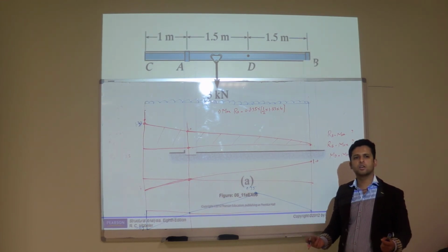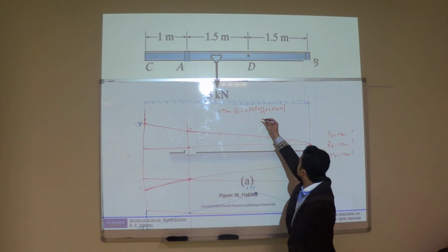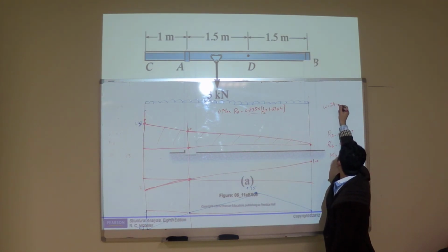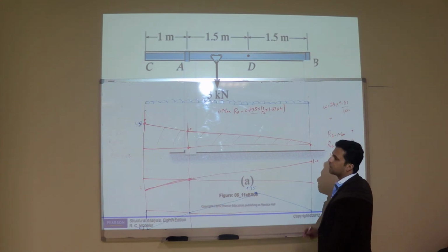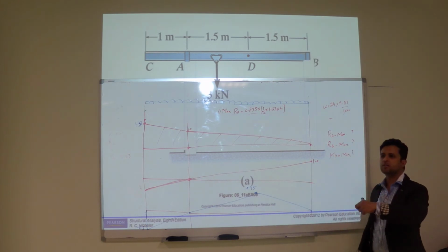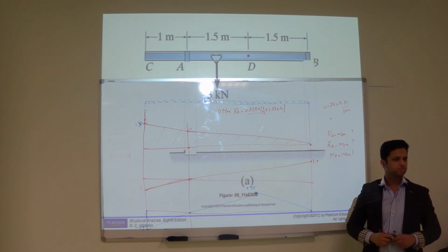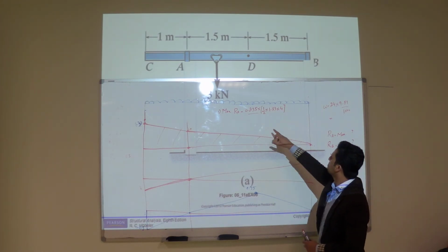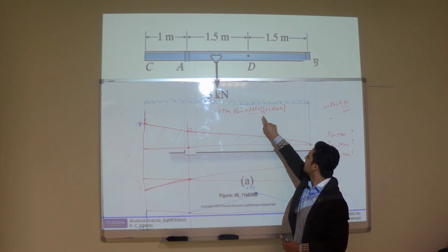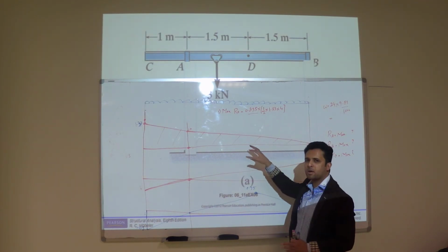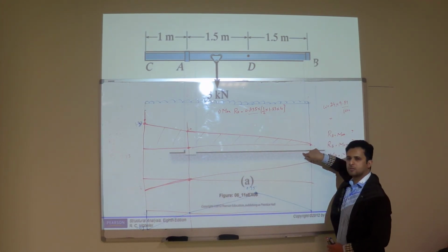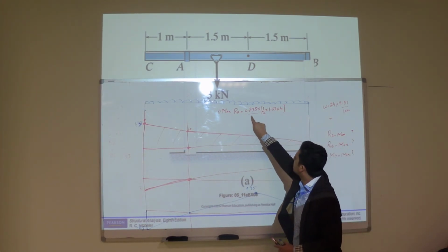So this 0.235 is the self weight W. It was 24 kg per meter, converted into kilonewton. Yes. This load is present on the full length of the beam. So multiply this load by this area. Why am I multiplying by this area? Because this load is present on the full length. So this is the reaction due to UDL.